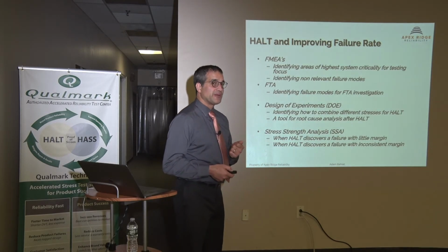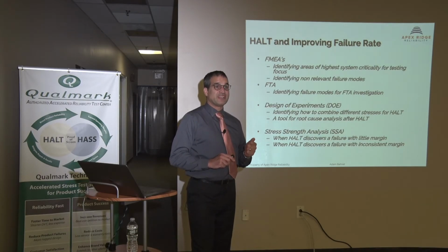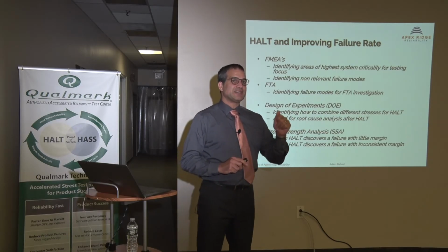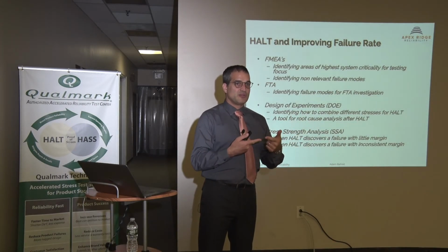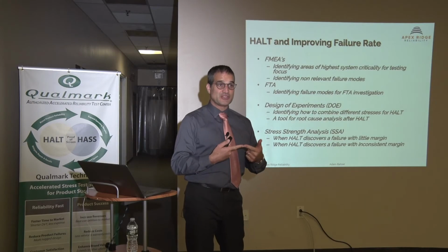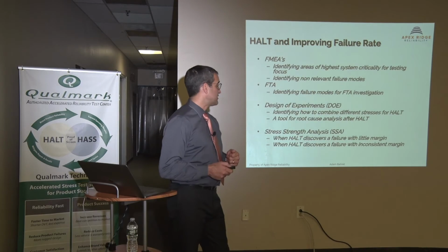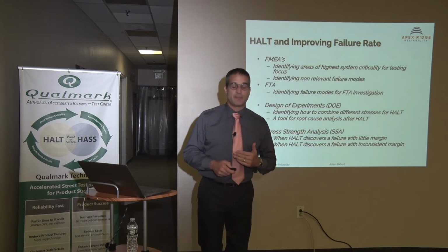We also have design of experiments. This is another interesting aspect of how HALT is very helpful. One of the important parts of design of experiments is you're finding interactions of stresses. Without design of experiments, we typically apply a single stress and look for a response, then a different stress and apply a response. What about the interactions of stresses? You need design of experiments for that. Well, what does HALT do? It allows you to apply combined stresses in a single test. So you can see how that links very well and are often used together. And stress strength analysis, right? This is about investigating margins.